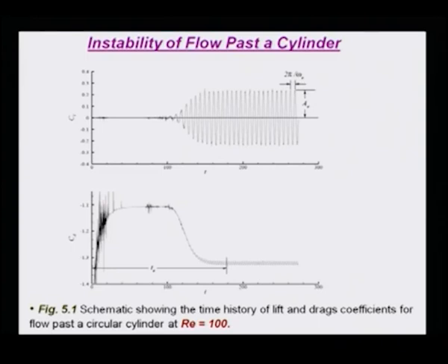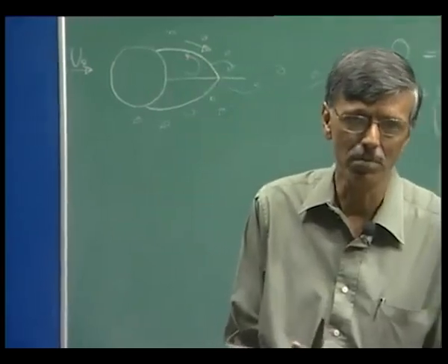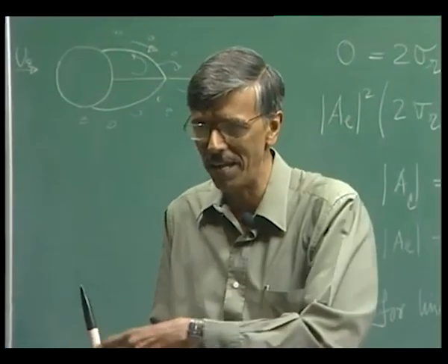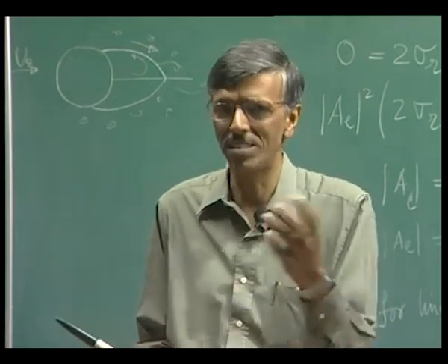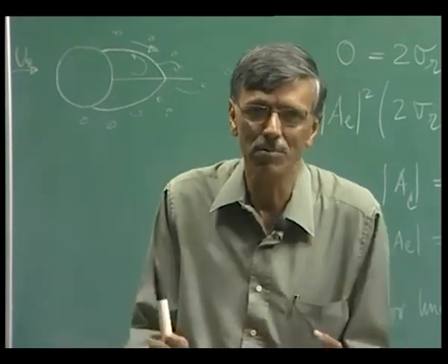The drag coefficient, after the initial transient, reduces, and then again it increases. Please understand this is plotted on a negative scale. So, the drag increases, and the drag variation gives a frequency which is not the same as the frequency for the lift. Why? Because in each complete cycle the lift varies once, whereas in each half of the cycle the drag keeps varying too.